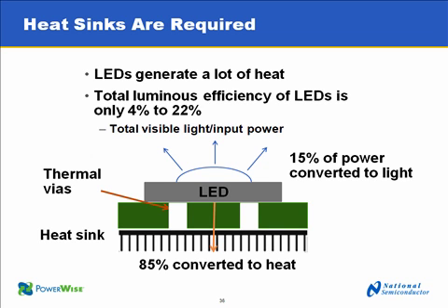What do you think the efficiency of LEDs is? Well, we know them as very efficient light sources, but if you actually look at the efficiency, which is the total amount of light that you get for your input power, they're only about 4% to 22% efficient using today's technology. So you're still losing maybe, let's say if they're 15% efficient, you're still losing 85% of your energy as heat, and you really need to get rid of that. And so we need to use a heat sink.